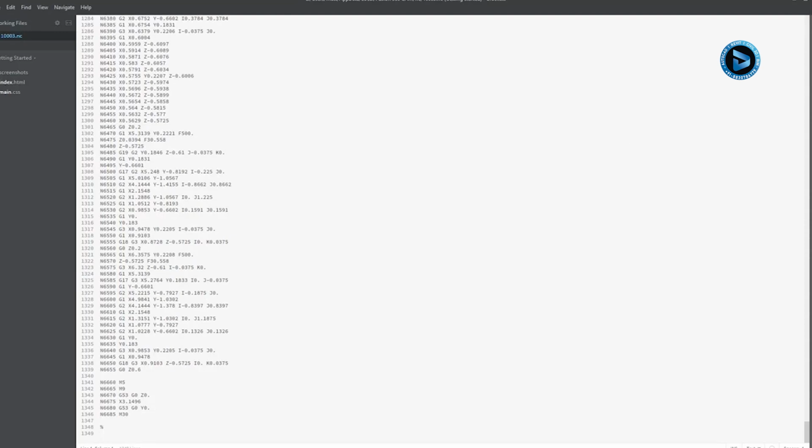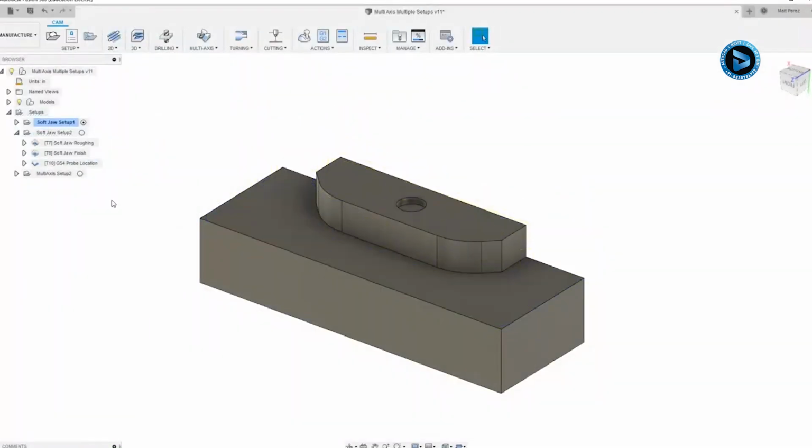So even though these are all in the same setup, we can simply program it once, and we can just decide what bits of code or what toolpaths we want to export. So this is a great way to use this over and over again. And we could also incorporate a potential stop in the program, so while someone's running it, they can just pause and end the program on the fly. But ultimately, it makes more sense to post out specific code that can either have or exclude the G54 location.